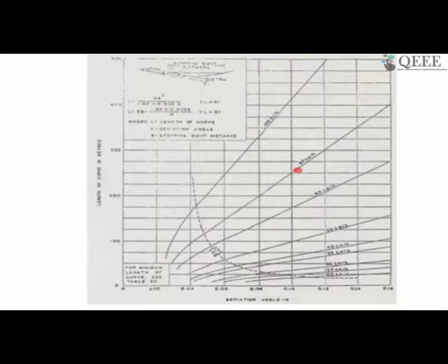Now a few other questions which I got, one is that from a safety point of view, which curve is more feasible, valley or summit curve? So from a comfort point of view, as I told you, summit curve is better. Now from the safety point of view, it all depends on the speed.